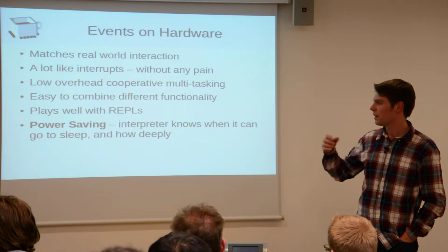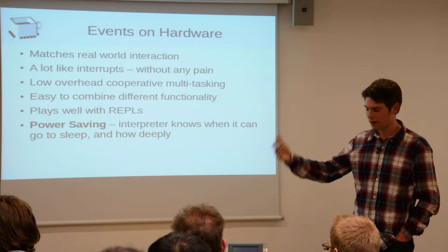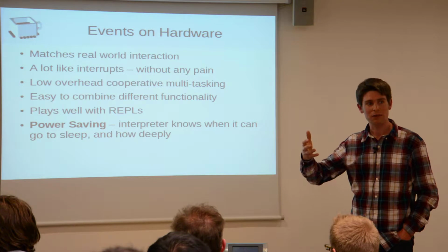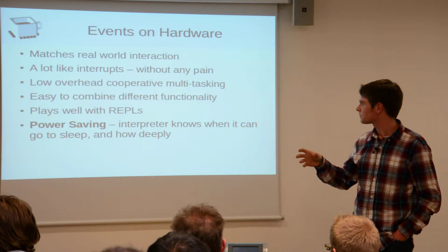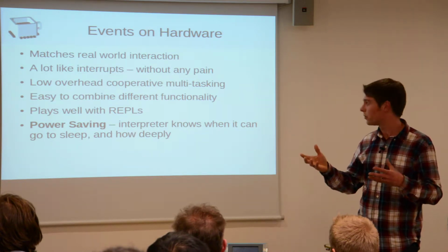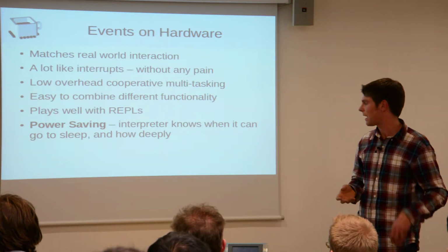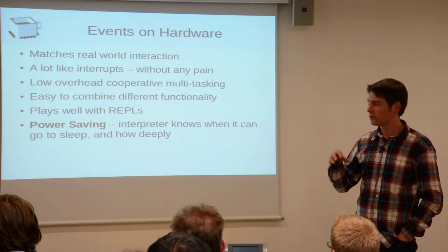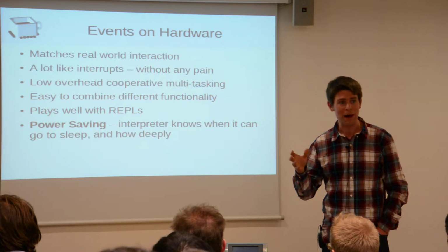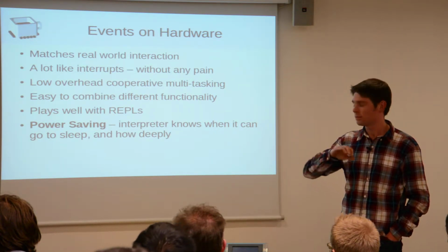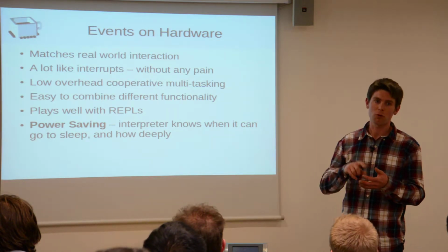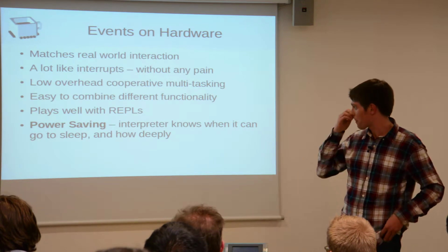And because of this, you don't have this idea of write code, run it. The REPL, the command line interface, runs at the same time as your code, filling in the idle cycles basically. So you can change stuff while it's in the process of running. And this also means that it's great for power saving. The interpreter knows when it can go to sleep, for how long, whether it has to wake up on interrupts or just the RTC or whatever.